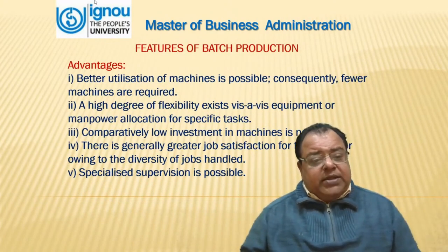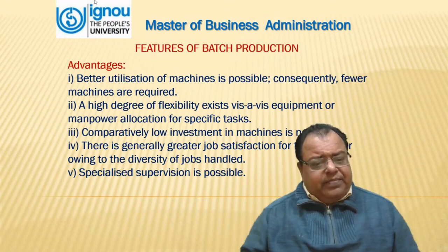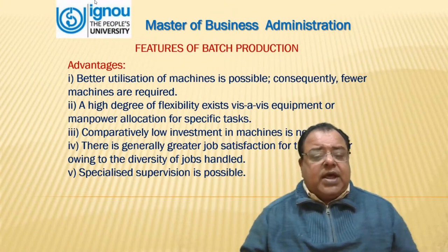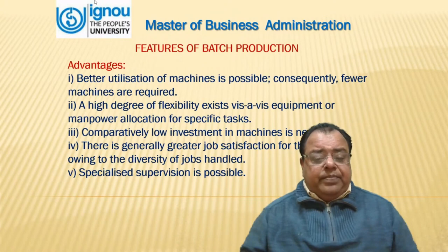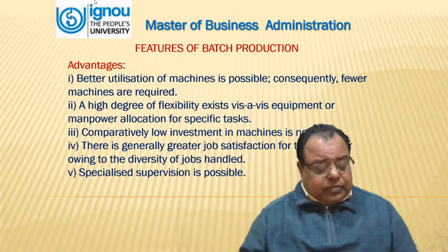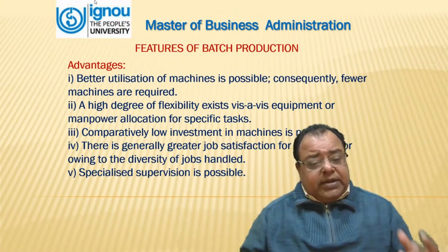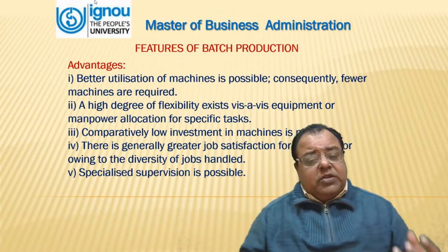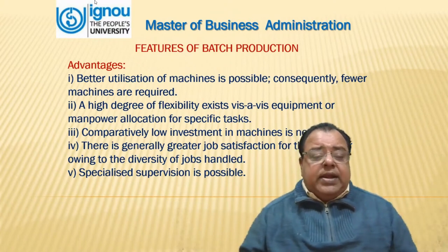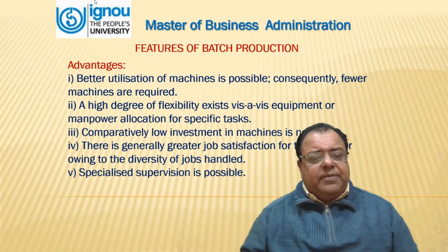We will start with advantages. Better utilization of machine is possible. Consequently, fewer machines are required. A high degree of flexibility exists vis-a-vis equipment or manpower allocation for specific tasks. Comparatively, low investment in machine is needed. Generally, there is greater job satisfaction for the operator owing to the diversity of the job handled, and specialized supervision is possible.